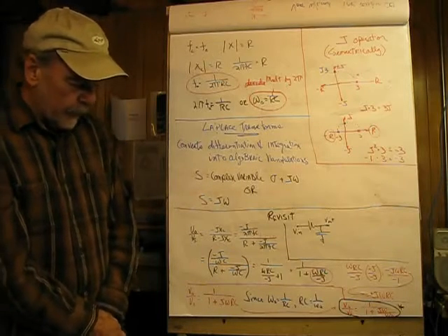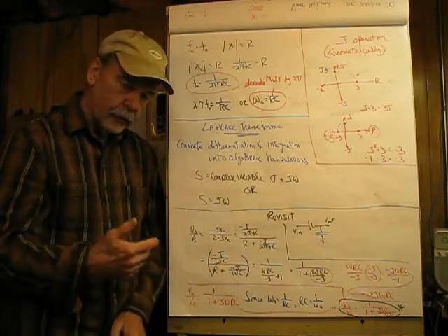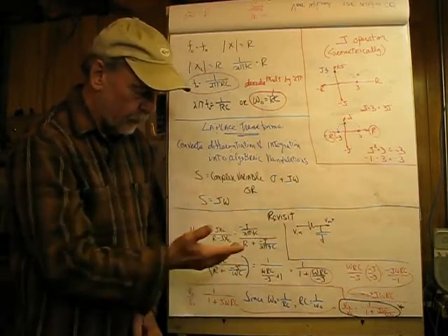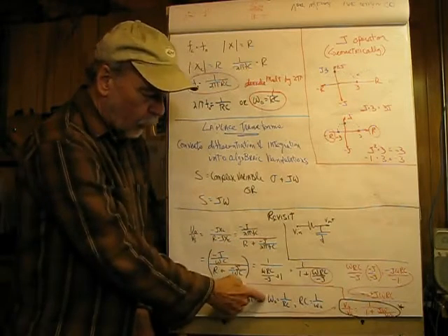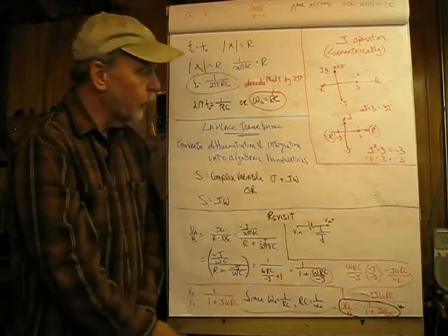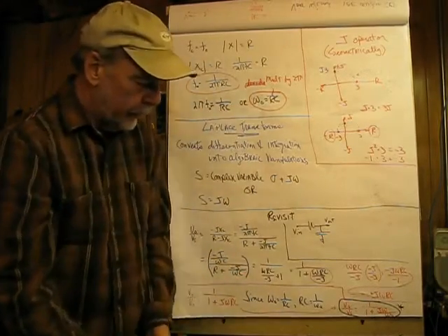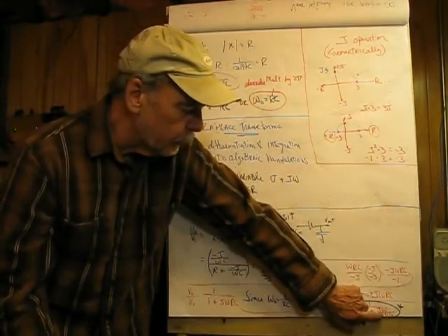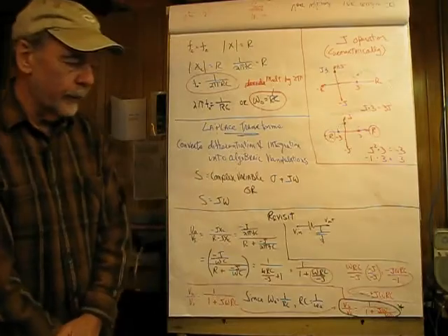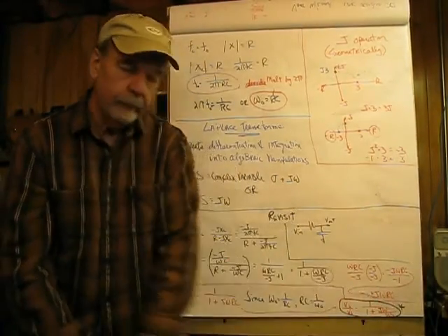And then, if we elect to substitute this, we'll be expanding on this shortly. So this is a busy page, I understand that, but we'll break it down a little bit. Omega 0 is equal to 1 over RC, as we see right up here. And if we elect to, taking this RC, we can replace that by 1 over omega 0 in the denominator, leaving us in the numerator j omega.